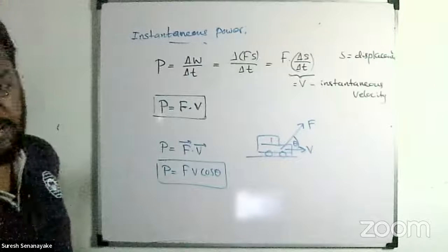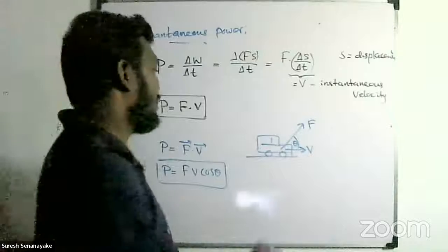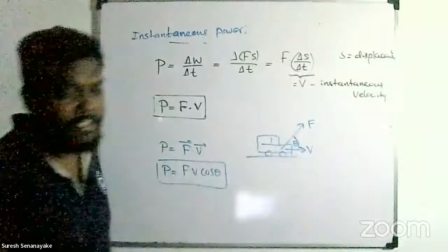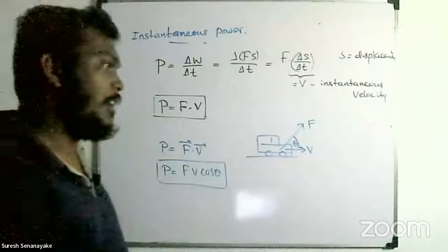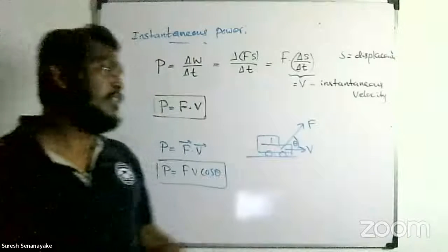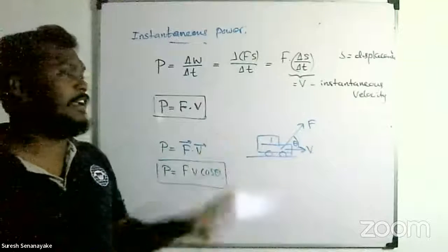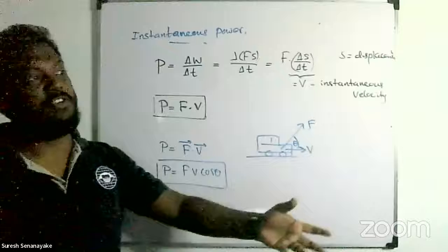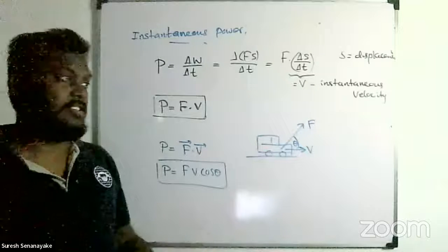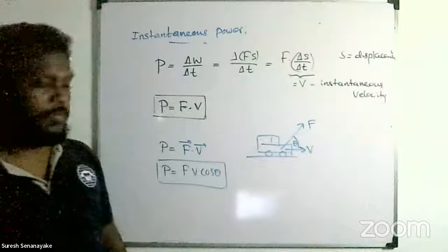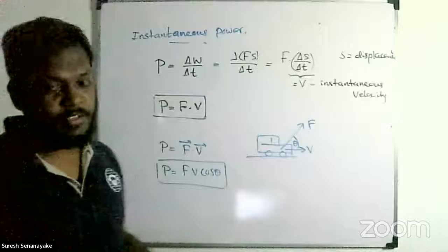For a vehicle engine, if you write the power of the engine, there's a force applied on the vehicle, which we call a traction. Traction is a force given by the engine to the motion. The resultant force acting on the vehicle is then the traction minus the resistive forces like friction and air resistance, which you need to subtract. So you can calculate the net force, right?